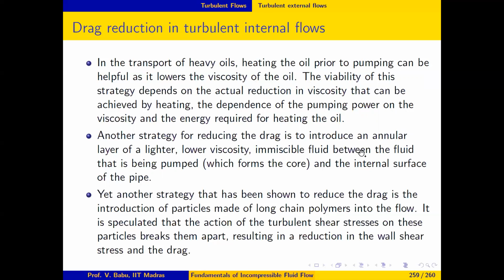Now, the fluid that is being pumped forms the core region in the pipe, and the fluid that we have introduced for reducing the viscosity forms an annular layer, and such flows are called core annular flows.